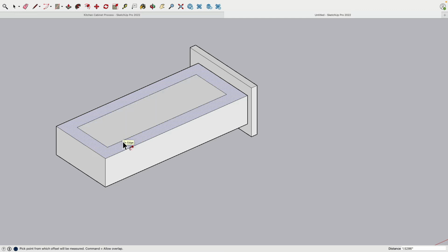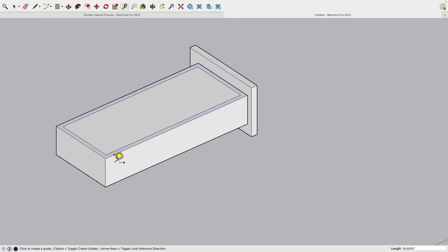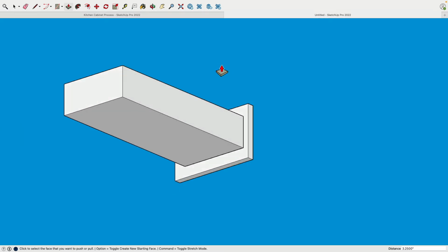The whole thing can have a material thickness of 0.5. So with the offset command, 0.5, and keep in mind that this was 3.5. So this centerpiece we bring down 3.25. You might ask yourself why. Here, check this out. At the bottom, we do the same. 0.5.